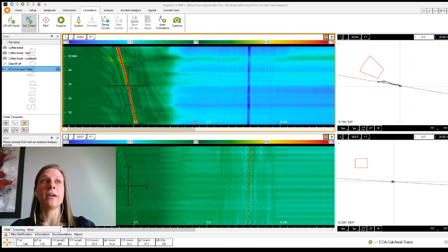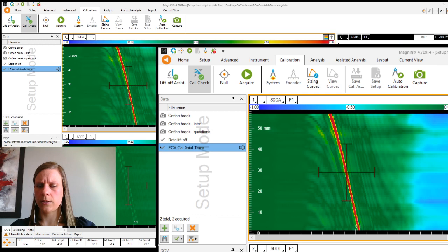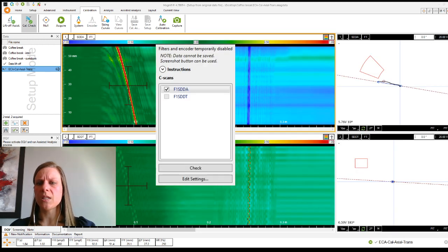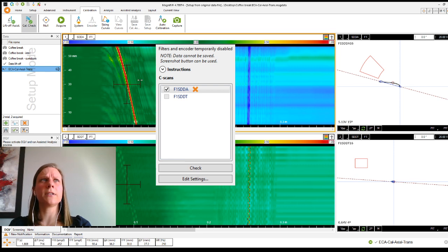where I set the tool to make sure that all channels lie between 4.75 and 5.25 volts, I will activate the actual check here, and when I click on the check button, I still have a small difference, and I don't know why. So the calibration is not correctly applied.